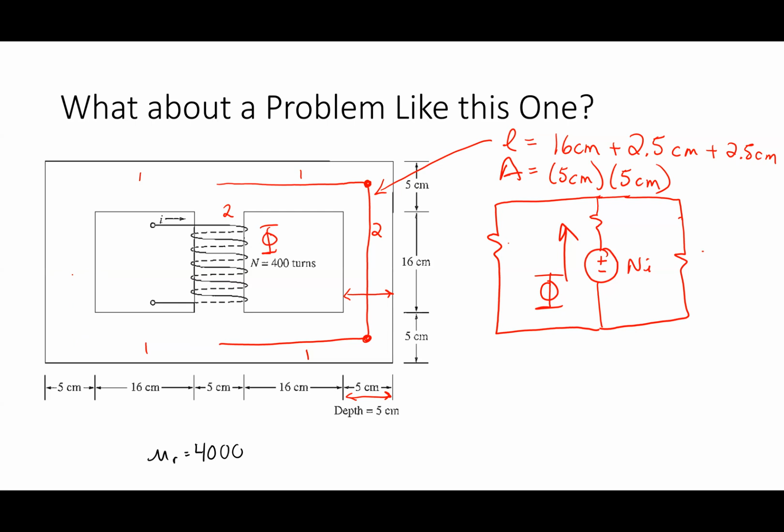If you do that, it'll work, so that gap won't have an effect. You could be picky about it, but with magnetics, you don't have to be. If that gap is big, it's probably a poor inductor anyway. If I made a good inductor, my gap should be small.